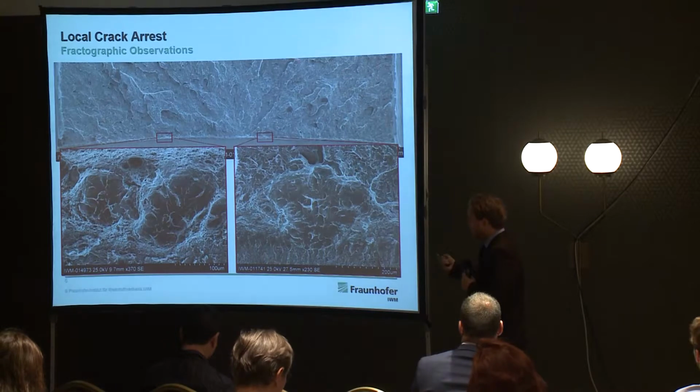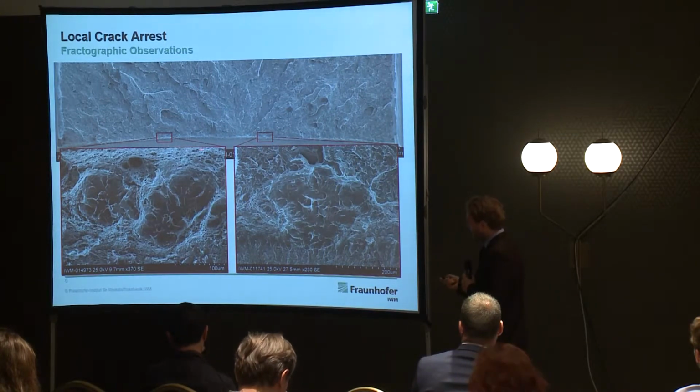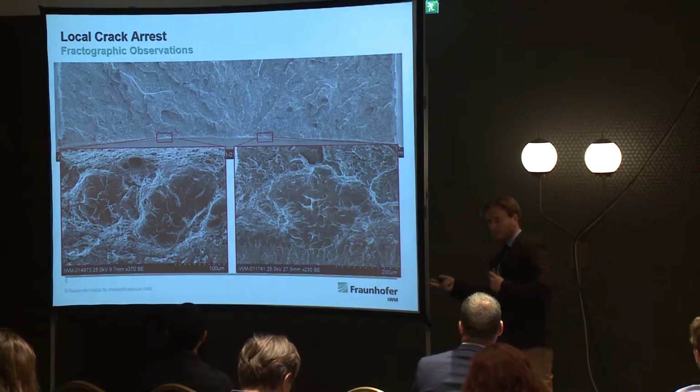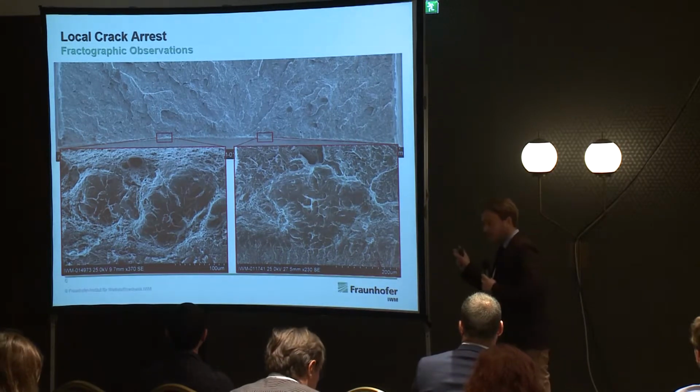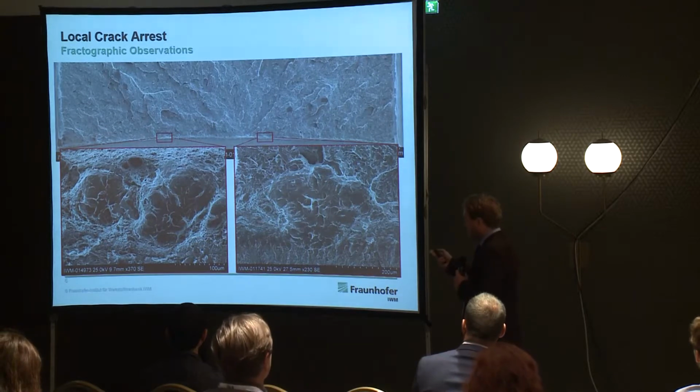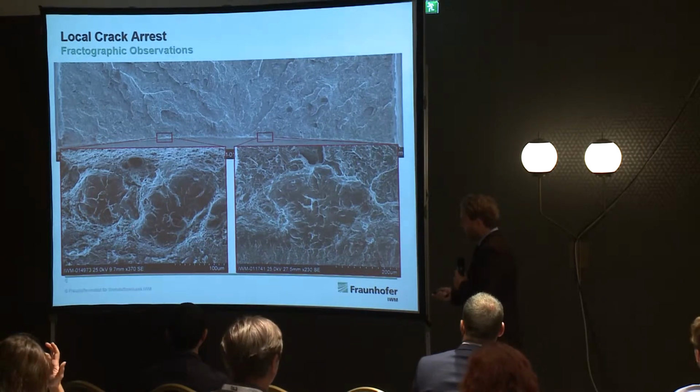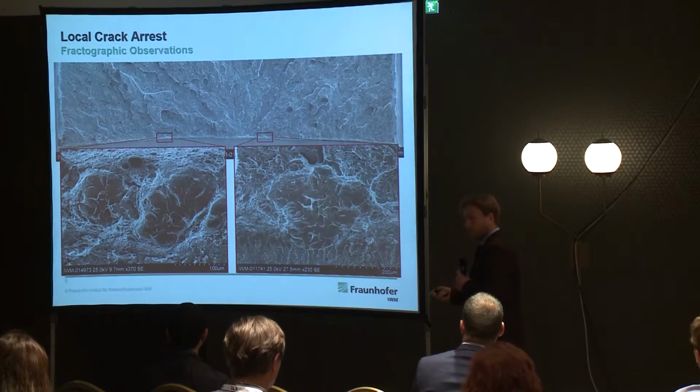Well, if we take a look at an SEM picture right here, this is the cleavage fracture, and we have a fatigue crack down here, and then upon load we have a ductile damage going on right here. And in the immediate crack tip region, we can observe on the fracture surface these island characteristic shapes, and they're also referred to as cleavage fracture islands.